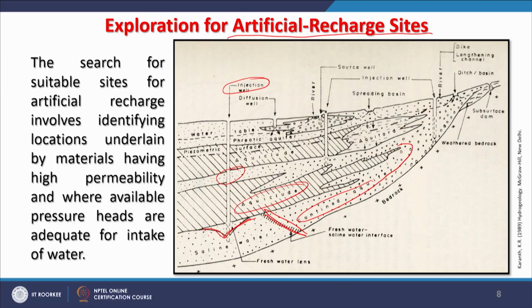So, entire geophysical or well logging work would be done, and the surface hydrogeological conditions would also be investigated, and once things are sure, the depth of the well which would do the recharging of our aquifer is decided. Preferably through these wells, we can go for confined aquifer conditions.